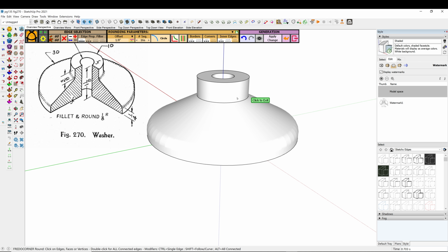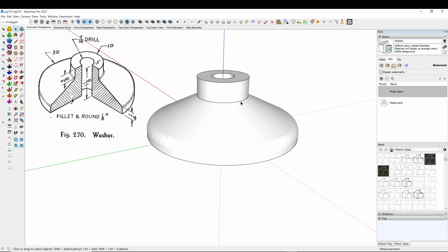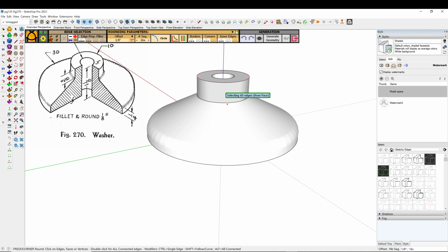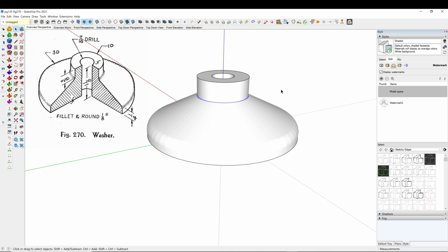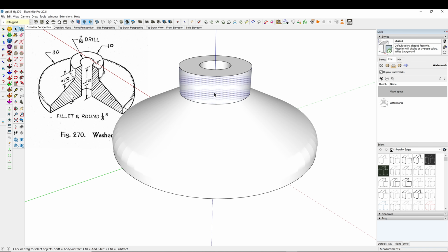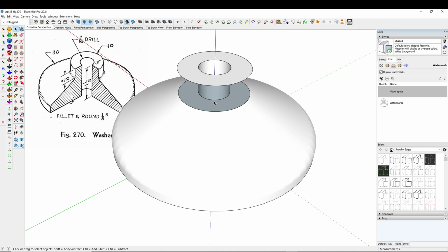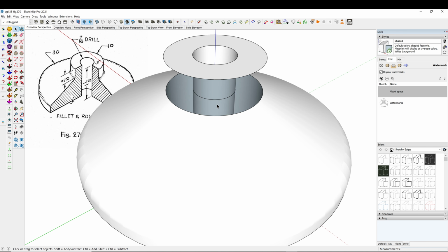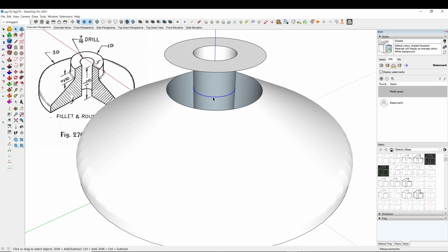So now I want to use the cove. I'm going to select that line, reactivate the tool, invalid match, no edge properties. So I think what's happening is that that face I created earlier is causing an error. So I'm going to select this, right click, hide. So there's that face from earlier. I'm going to delete that. I'm going to delete that ring.